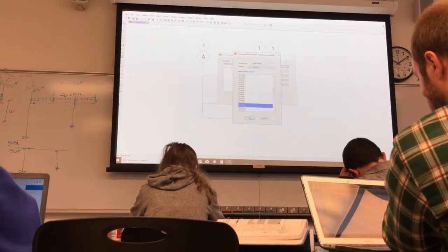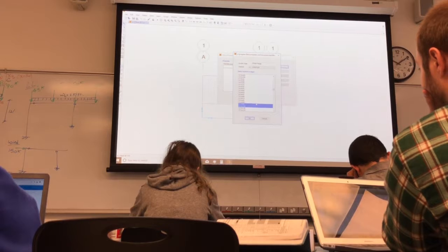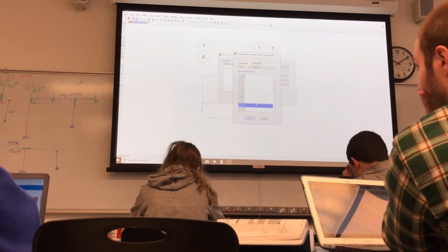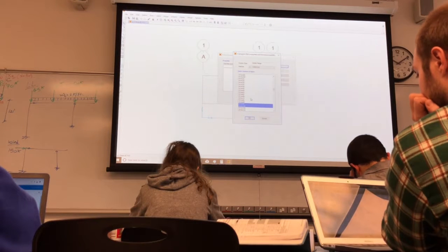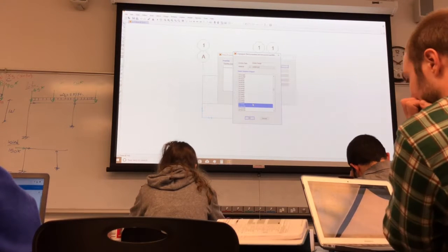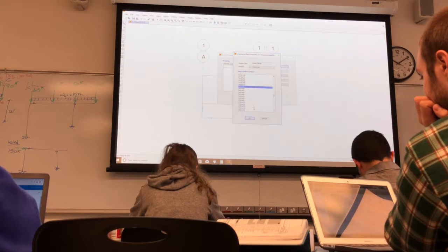So which 3 did you select? The ones here, right? Because that's only the ones I need. These 3, right? I don't need all of them. I just need these 3. Because one column is a 14 by 109, one is 14 by 99, and then the beam is 21 by 44. So that's all I need. If I had more sections, I would have selected more.